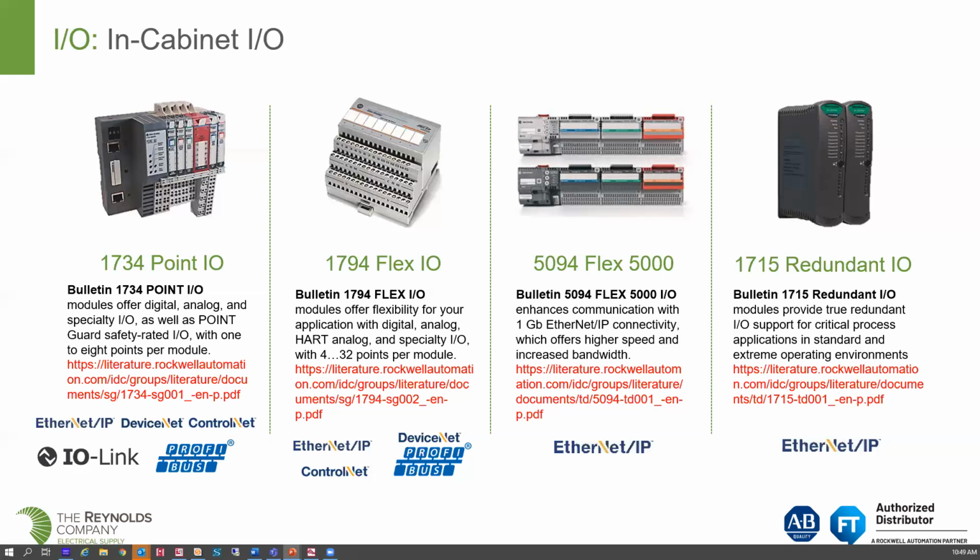And also the cards can be used in either a simplex or a duplex fashion. So if you have certain safety loops that you need to have duplex, you can certainly use 2 cards. But if some are not part of the safety loop and you just want to do a simplex, you can put 1 card in there. So it works out very well. The wiring terminals are on the top. It is a different form factor, and some of you might say, well, this looks a lot like the ICS product, because this is the advanced IO that's been adapted for our use.